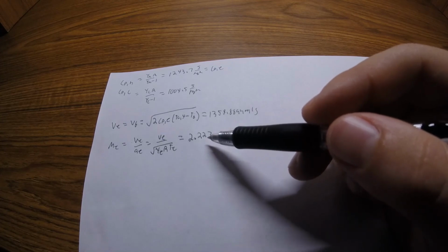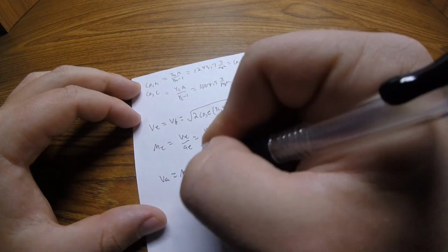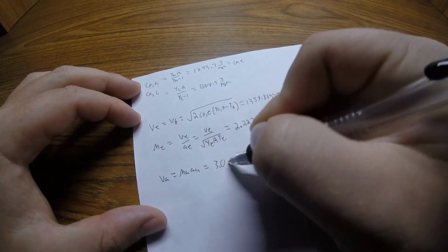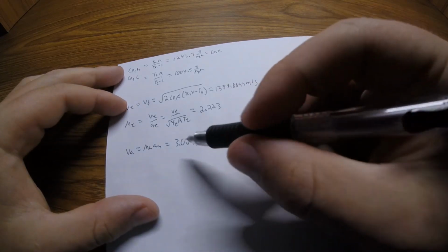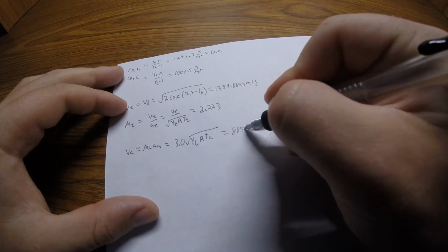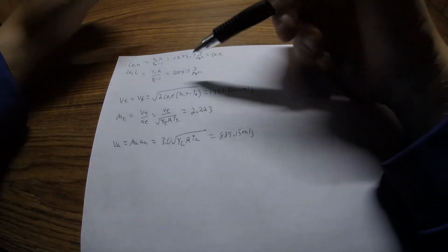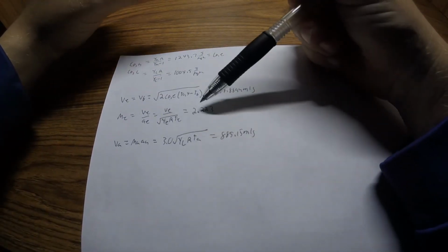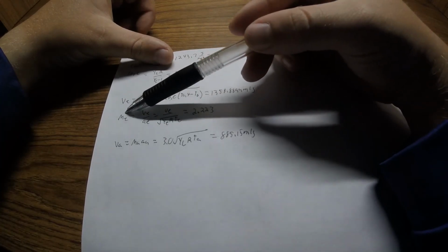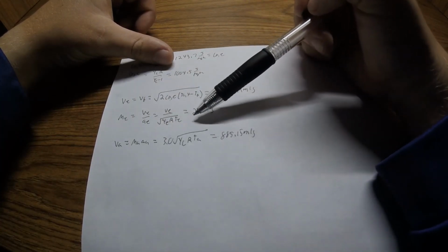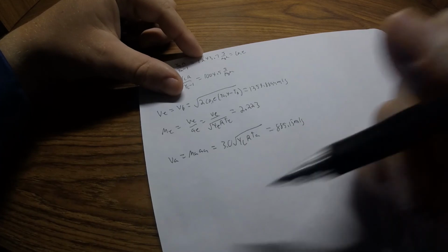But as we'll calculate right now, the speed of the air, so calculate V_A equals M_A times a_A, 3.0 times the square root of gamma cold, R times T_A. Now this will equal 885.15 meters per second. So as you can see, the velocity of the air coming out of the back of the engine is faster than the air going in, but the Mach number at the exit is less than the air going in. Pretty interesting. For an ideal ramjet, the Mach number at the exit will equal the Mach number at the entrance. So how about that?